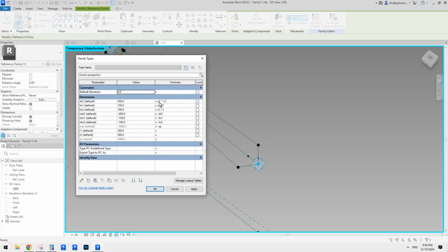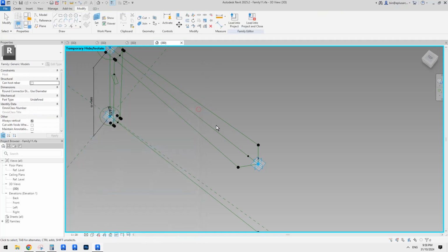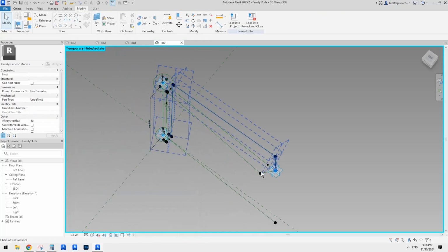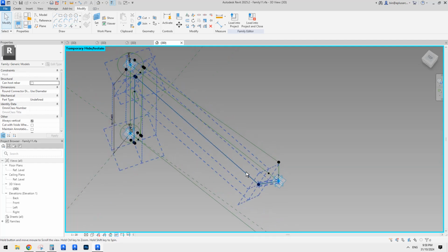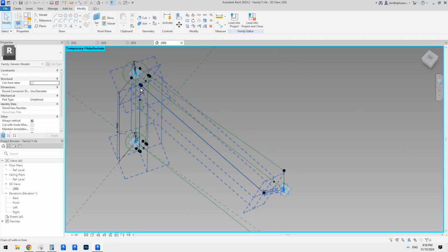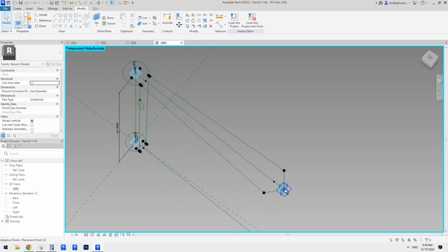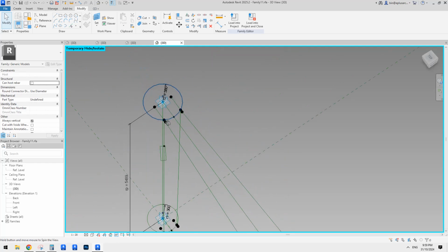You can see I use R2 times 1.2, but you can adjust that number if you want to. If you want wider, you can just increase that 1.2. If you want narrower, just reduce that number. So this will create a reference line. From this base point, go up here, back here, down, and always keep that.